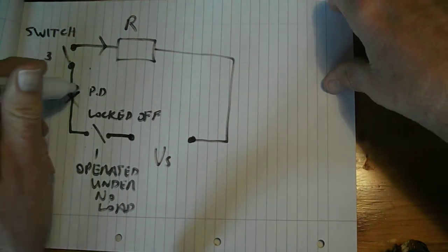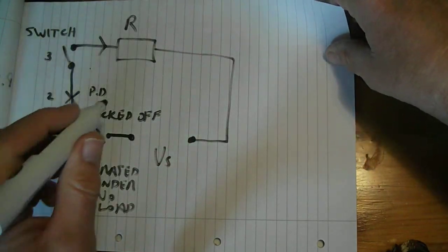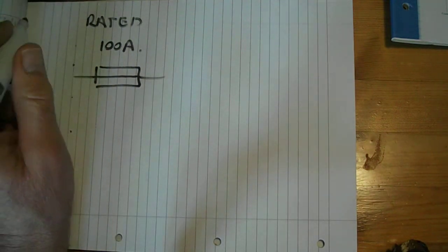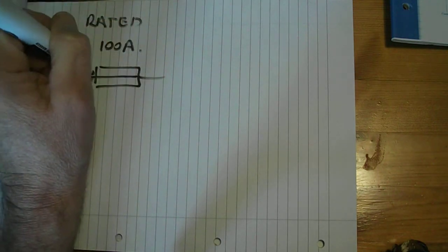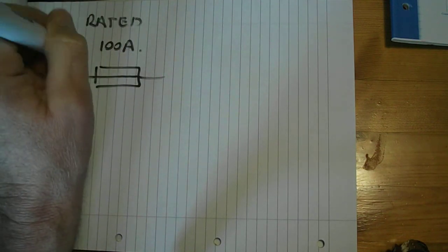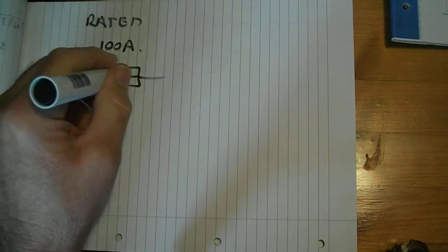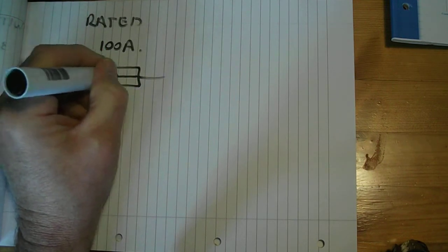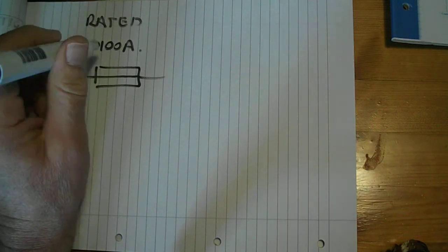One of the other types of protective device that can be found in this part of the circuit is a fuse. And the symbol for a fuse is simply a rectangle like that with a wire going through it. And the fuse always has a rating, for example 100 amps. And that's the rated value. And what that means is that this will operate continuously with a maximum current of 100 amps. If it goes over 100 amps, then it'll probably start to get warm, and as the current goes up and up, it will start to get very hot, and eventually it will melt. If the current goes up very, very rapidly, then it will what we call blow very quickly. So this short piece of fuse wire inside the fuse will actually melt very quickly and blow very quickly.